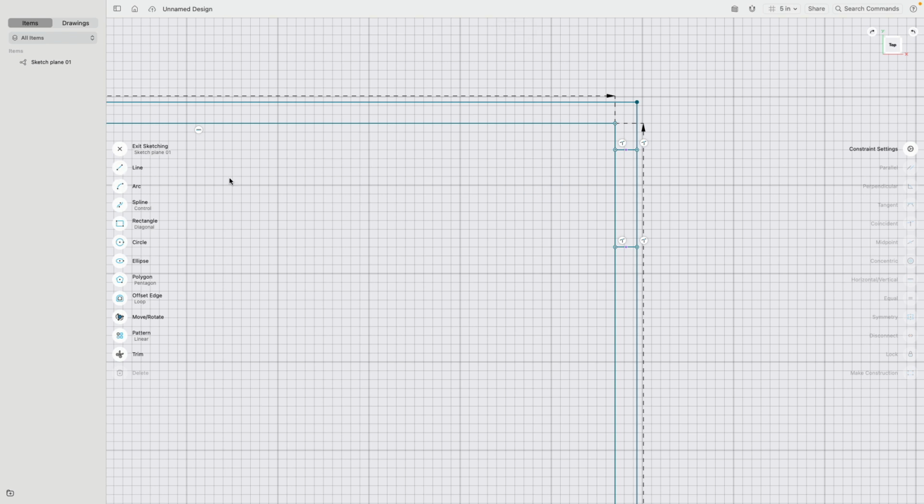So we stopped the drawing command. Shift click these two lines. We want to make sure they're always horizontal. Then now I can select this point and say, well, this door is actually 40 inches wide, and from this wall corner it is 36 inches away. And you see it moved that whole rectangle.